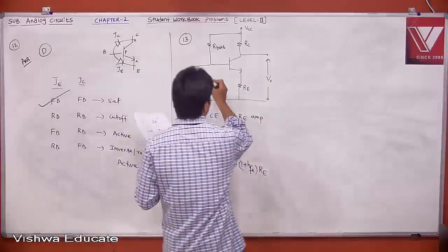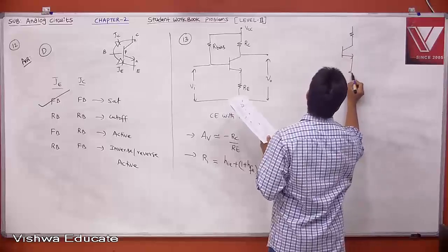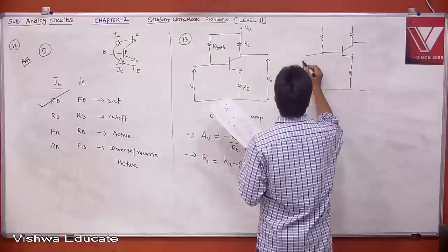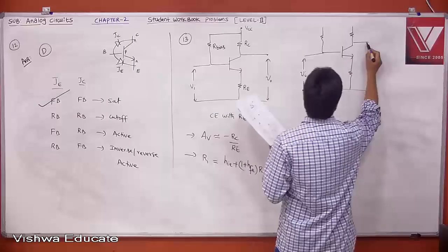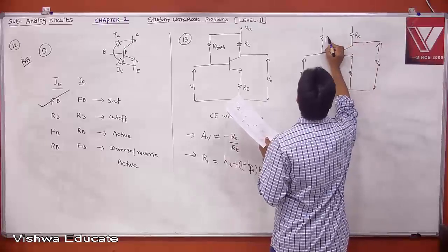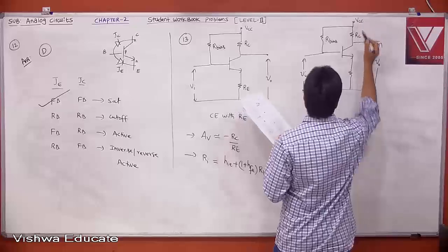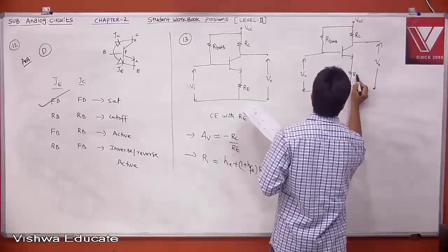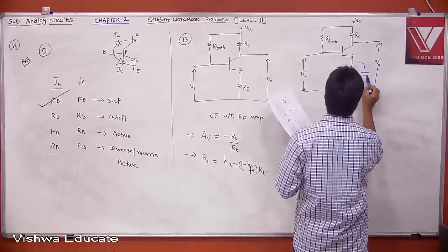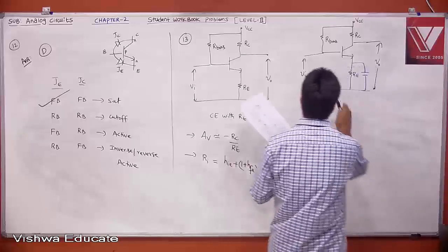The moment you keep a capacitor in parallel, let us say a capacitor is kept in parallel, then it is bypassing RE.